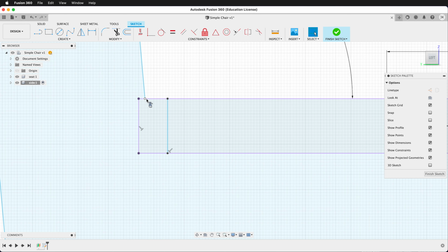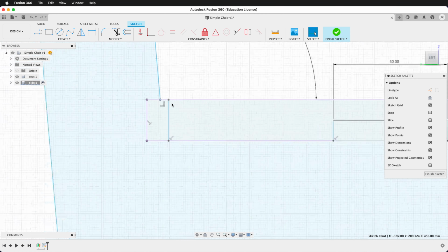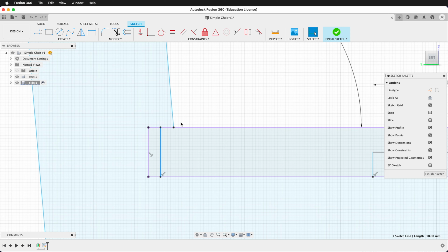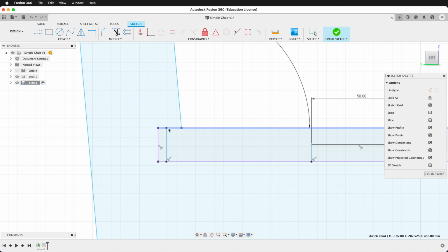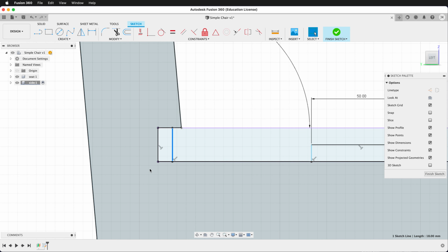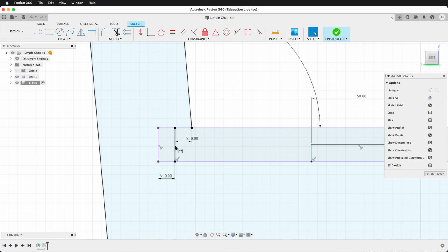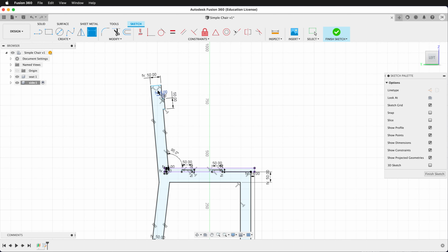And then we want to move this over just so we can see what's happening to the lines. We want everything to overlap half ply here. So we want this line to be in the front, and then there'll be a little bit of overlap of the two pieces. So we want this dimension from here to be ply divided by 2. And then we want the same dimension here. So we want to go from this point to this point and make this ply divided by 2. So now that's really starting to lock down some of the pieces.